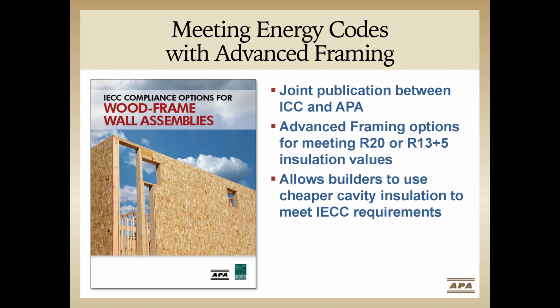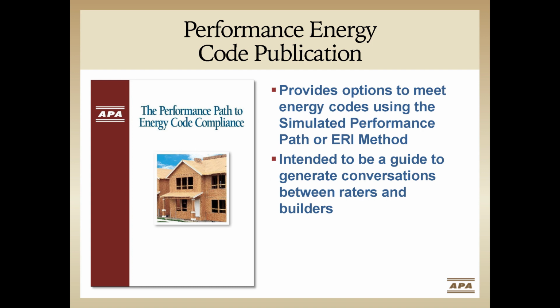The advanced framing details that we have and will discuss can be used to comply with the requirements of the IECC. This document that APA co-published with ICC provides 5 code-compliant options to meet the prescriptive R20 or R13+5 requirements. These assemblies allow the builder to use a cheaper cavity insulation to meet the IECC requirements and helps the energy code challenges to be overcome in a cost-effective manner.